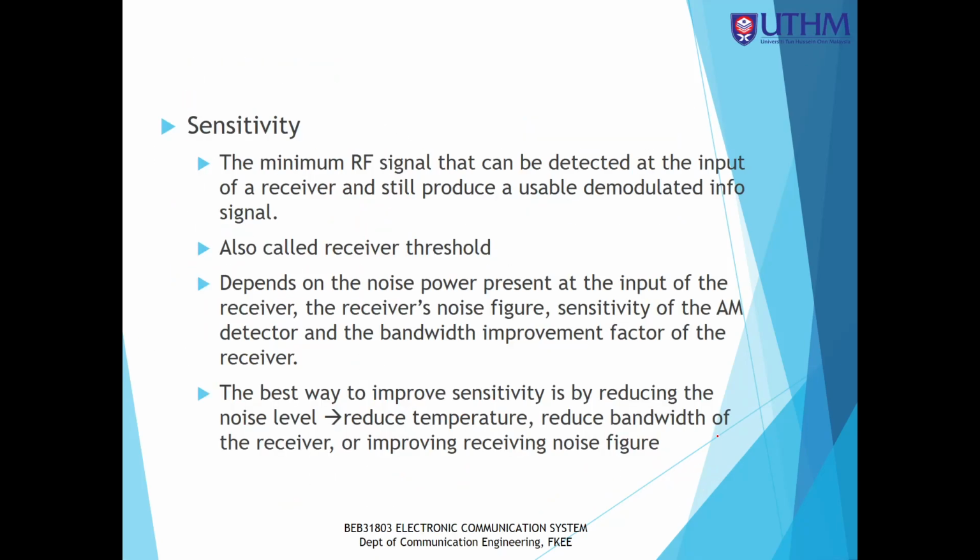Other than selectivity, there is the sensitivity parameter. The sensitivity parameter is the minimum RF signal that can be detected at the output of the receiver and still produce a usable demodulated information signal. So when we receive the signal,